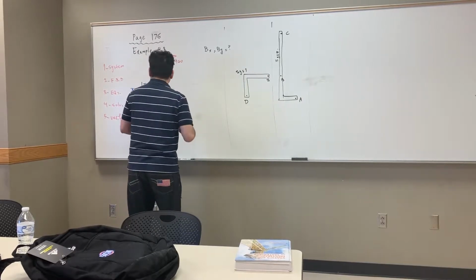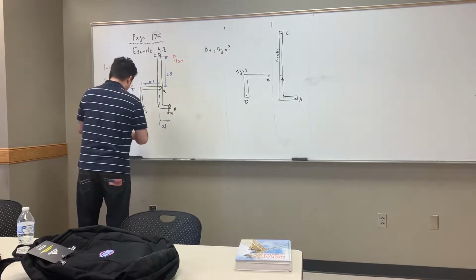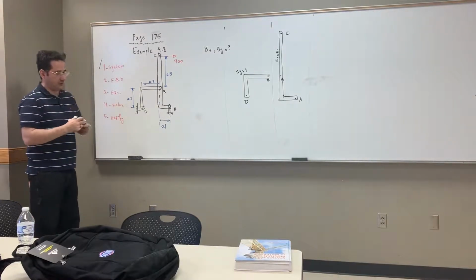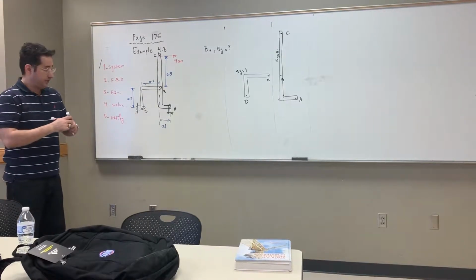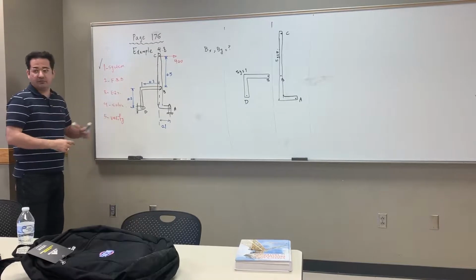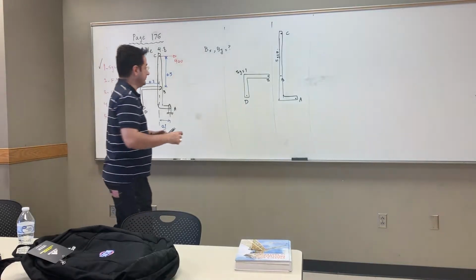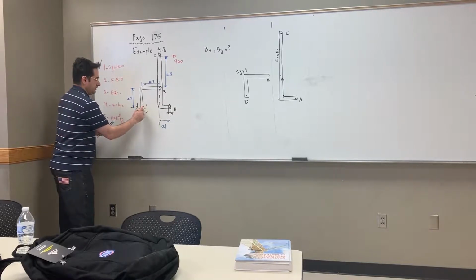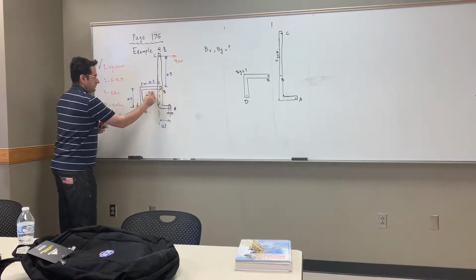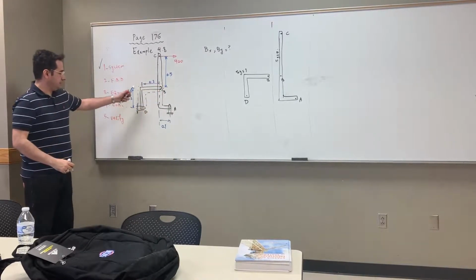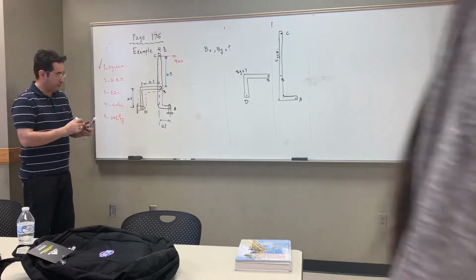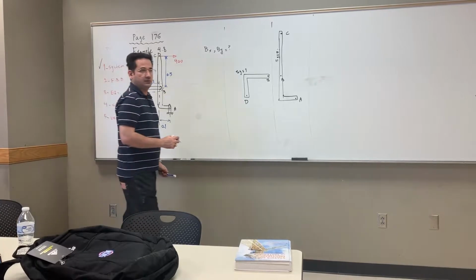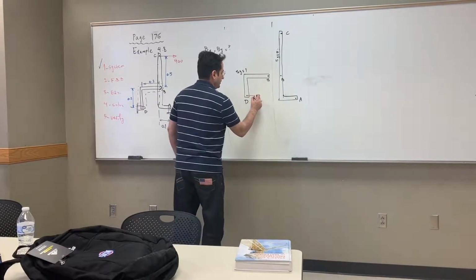Okay. Now, I check mark step 1. I did my system. So these are my system 1 and 2. Now draw FBD. For every system, we do FBD. So here, again, if I draw that dash line envelope and start walking to get surface forces, how many forces and moments do I have at D? DX, DY.